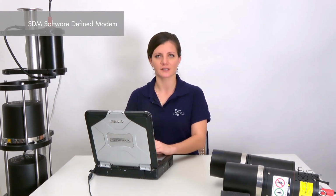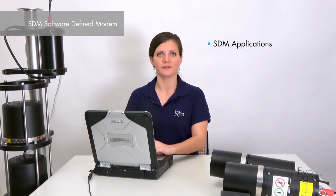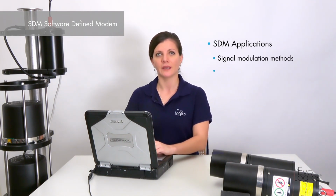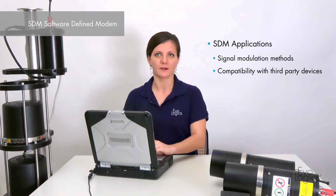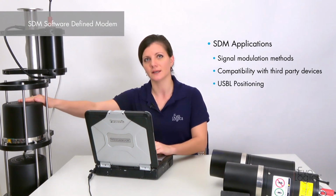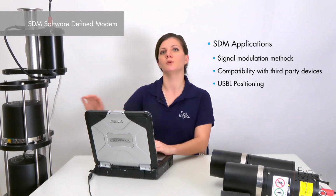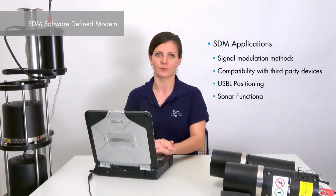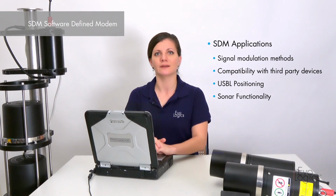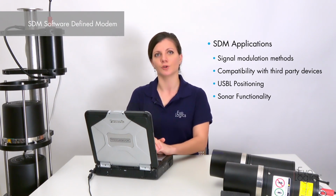What are the applications for SDM modems? These are development of signal modulation methods and their prototyping, enabling compatibility with third-party devices on a user level. For devices with a built-in USBL antenna, another application is developing new methods for ultra-short baseline positioning. And last but not least, with SDM modem, you can implement sonar functionality on acoustic modem hardware.